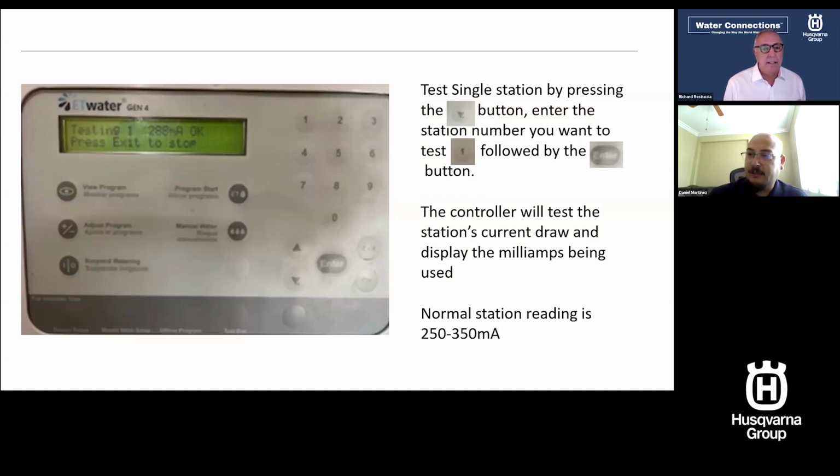What that does is, you're activating the station, you turn the station on, and then the check status will ask the controller, hey, what's going on? And it reports back, hey, I'm watering this station. If you have a flow sensor, it'll give you the gallons running, and it'll tell you the milliamps draw for not only the master valve, but the station you're testing. Wow, a lot of information available without being at the controller. Correct. I would do that before sending a truck out for sure.